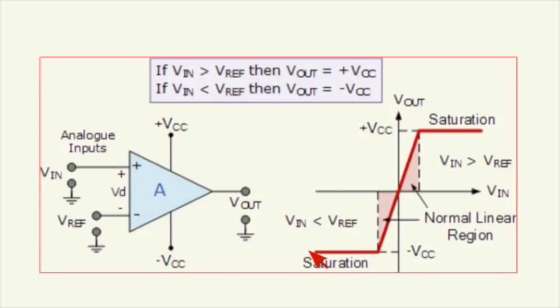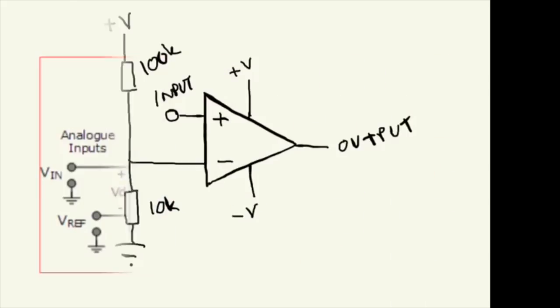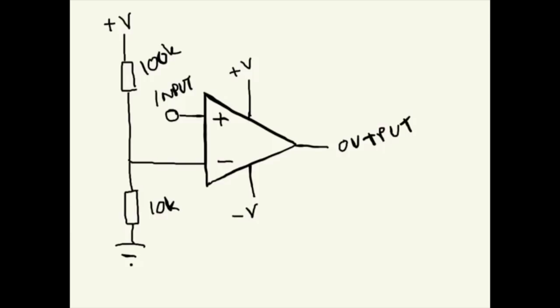And that is how this would look when you raise the voltage input. So when it goes over the threshold, it goes from negative voltage to positive voltage. Here is a common example used in many synth designs and modular modules.